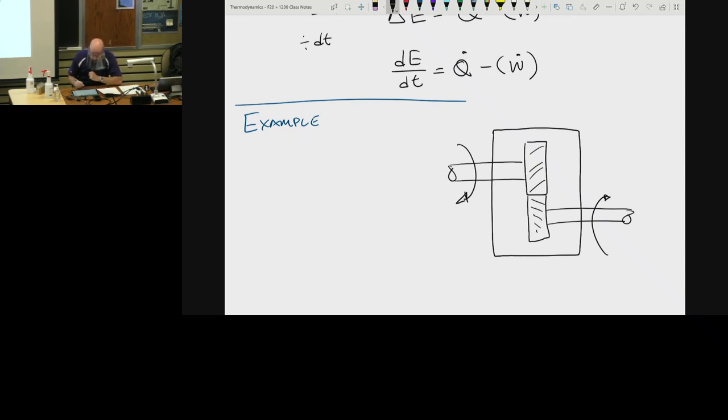And I want to say that this gearbox is running at steady state. Oh no, that phrase, steady state, is coming up. Well, that means we're not just starting up this gearbox. It's been running for a while, steadily and constantly. That's what I'm analyzing at steady state, and I want to do that for almost every thermal question I work with. It receives 60 kilowatts through the input shaft. So this is my input shaft, and it's 60 kilowatts of power, the rate of work, coming into that first gear. It's going to deliver power out from the second gear, but we don't know what power is coming out right now.